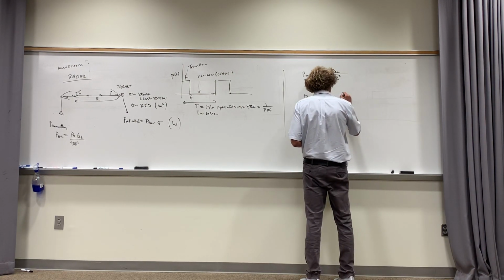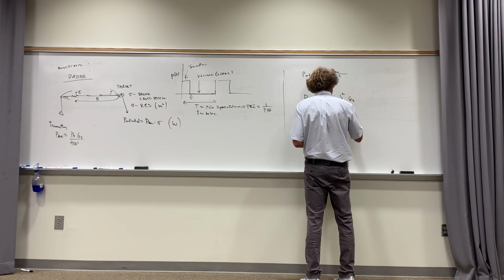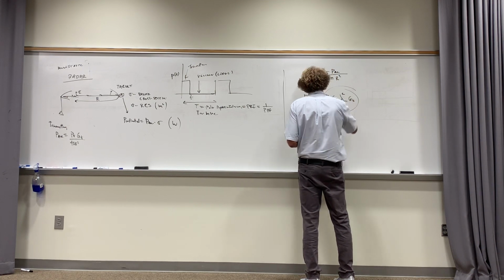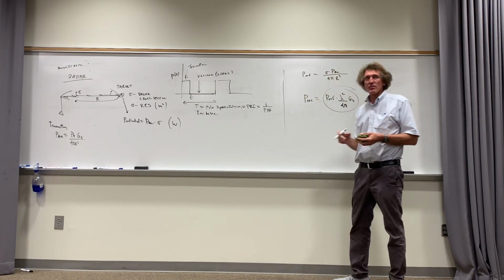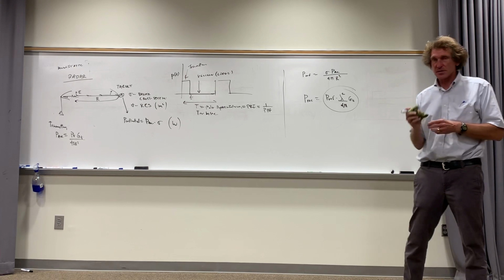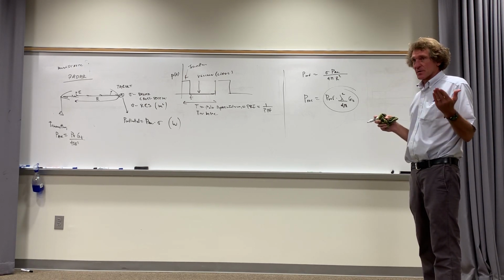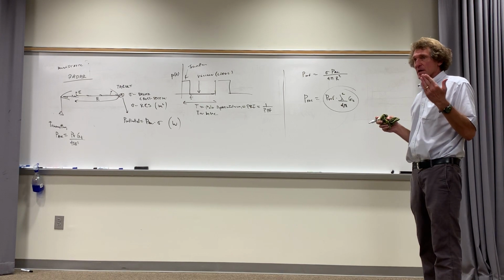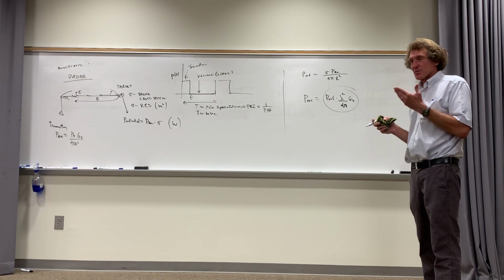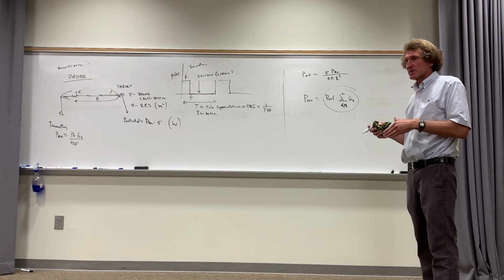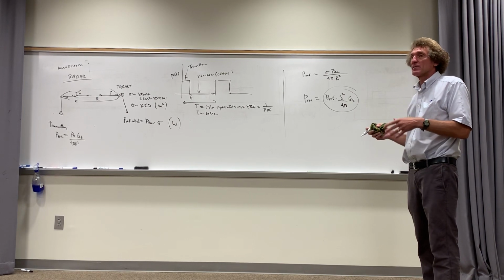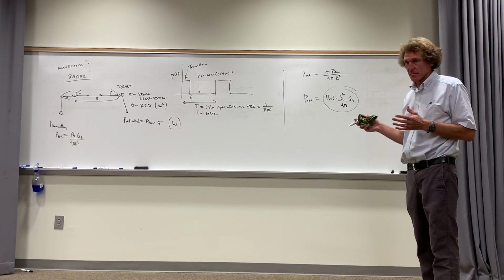It's lambda squared over 4 pi times the gain of the antenna. And this would be the gain of the transmitter too, because they're the same. And that would be the amount of power received. Now I'm going to give you one single equation in a second. But you follow the thought process. You have transmitted power density, reflected power density, and then reflected power received.